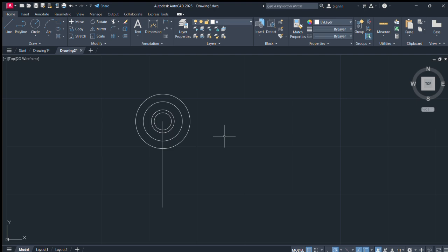Alright, next up from the diagram, we can see that we have a distance at the bottom of 12. So if we cut from the midpoint, we're going to have an offset in both sides of 6, 6. So we're going to draw an offset from the center line of 6 to 6. We select the offset tool, enter a distance of 6, then offset it both to the right and to the left, just as you are seeing.